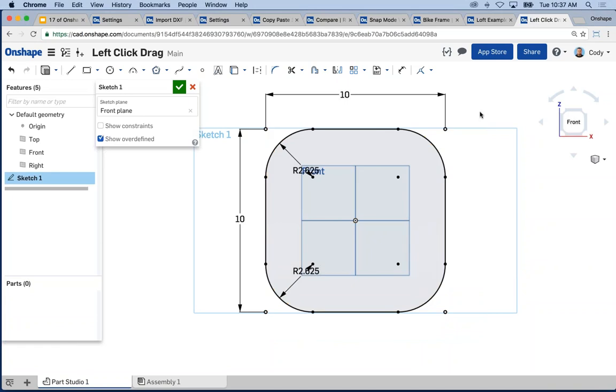But a big tip that I have, and it's just a common scenario, is I want to offset everything associated with this chain of geometry. So I select offset, and again I use the left click drag. So instead of left clicking an individual piece of it, I left click drag one piece and it will grab the entire chain of entities. So I don't have to left click individual pieces. I don't have to window select beforehand. I just left click drag one of the pieces and it will automatically grab everything.